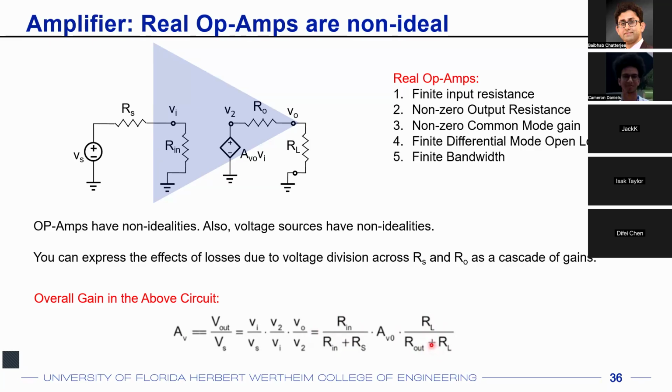So that's why you can directly understand the implication in terms of a real versus ideal op amp: you want your Rin to be infinitely large and Rout to be infinitely small. And this is the reason. You want to stop those voltage divisions. And that's why you want to design even your real op amp with a very high input impedance and a very low output impedance.